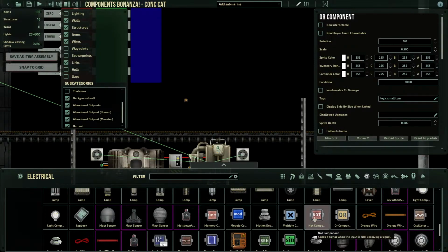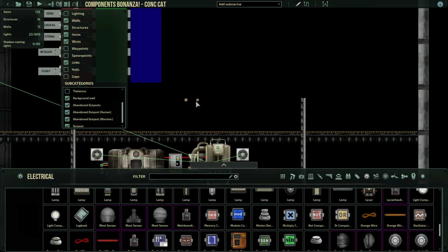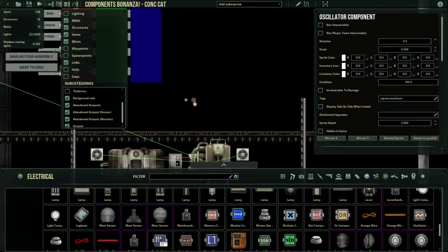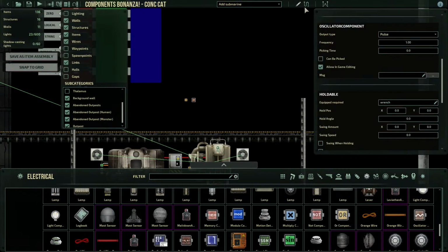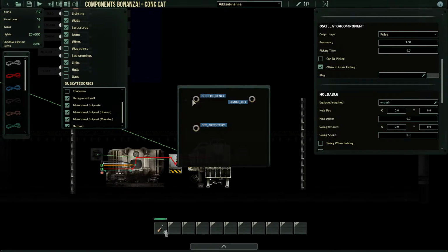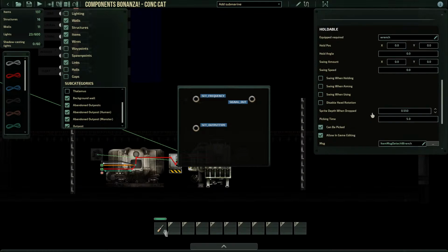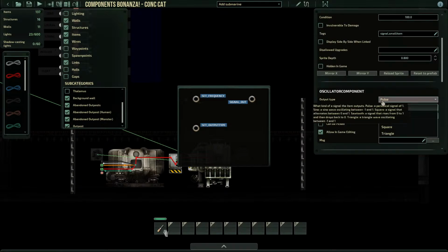Okay. So that's OR. Oscillator. The oscillator has 2 inputs. It has the frequency set point and the output type set point, and the signal out is determined by those 2. There are 5 modes. 0 through 4 are the indices. That's important. If it's in mode 0, that's the first.